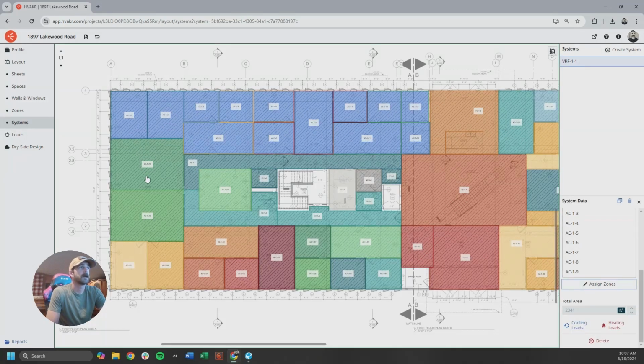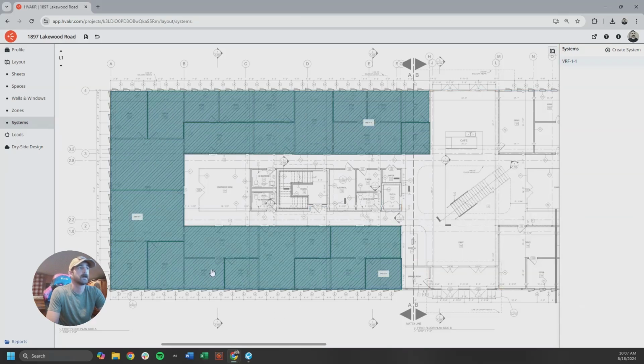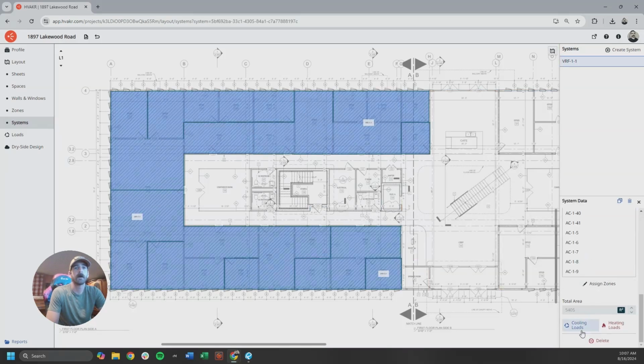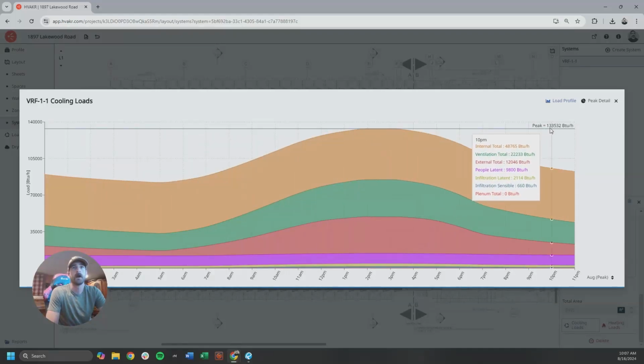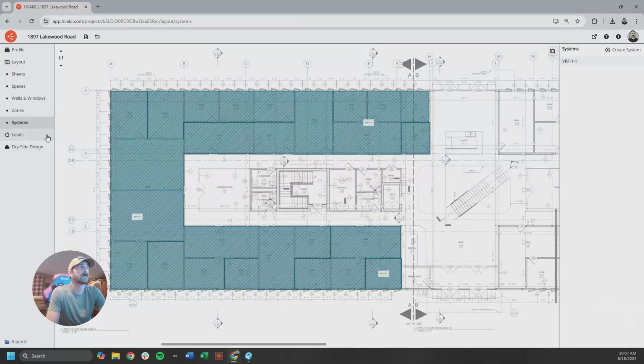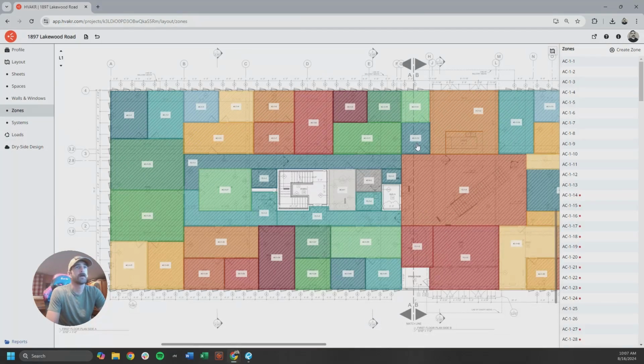There's a bit more capacity here. I only have, looks like 13 zones on it, so I've got more room. I think I can cover this entire quadrant with 1 condenser unit. So let's consider this VRF 11. I'm going to scroll down here and check my total load. I'm still well within the 430,000 BTU capacity, and it looks like I have 13, 14, 15, and then 31 to 41 is another 10, about 25. So yeah, I'm well within how many boxes can go on one system.